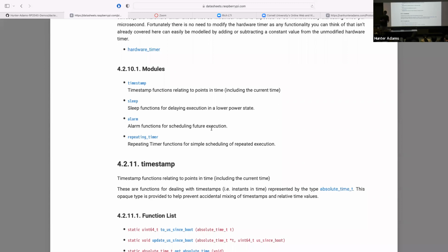So there's levels of abstraction here. What the alarm pool allows for you to do is to associate a bunch of different callback functions with a single one of those low-level hardware timer interrupts. My model for this, and from the documentation I can't tell if this model is technically correct or if it's just a model, is very similar to the way you might set up GPIO interrupts on a different microcontroller, where GPIOs are often arranged into banks. There's a certain set of GPIOs associated with GPIO bank A or 0 or whatever the convention is for that microcontroller.